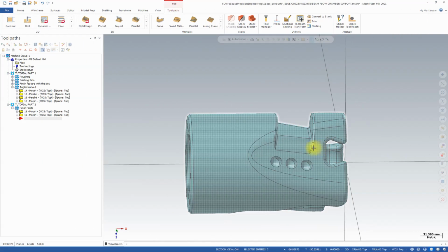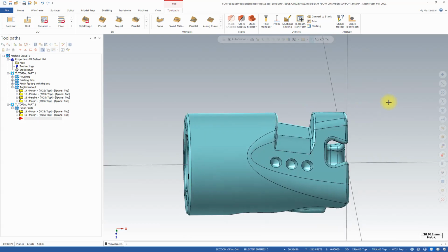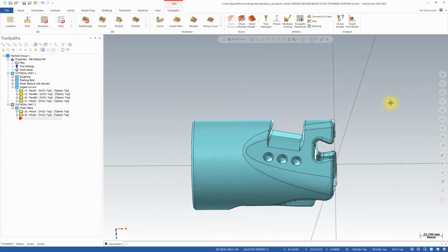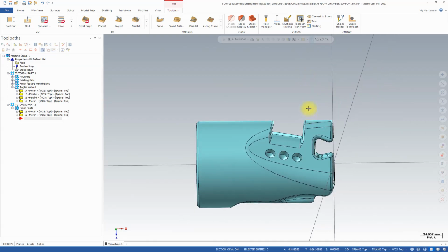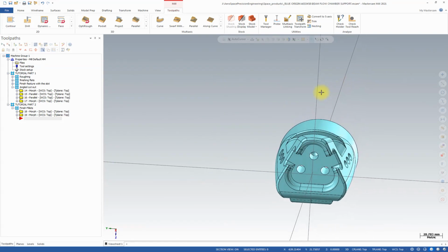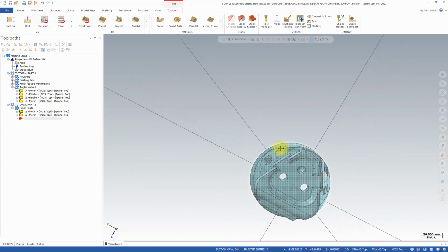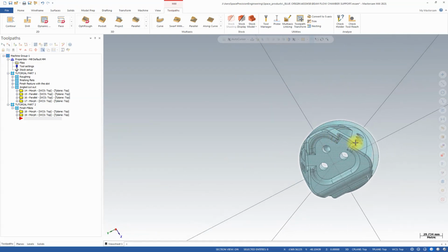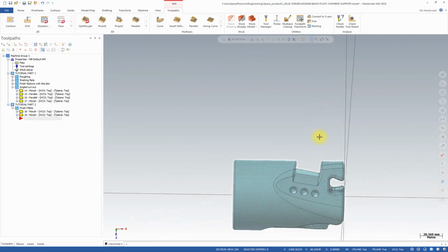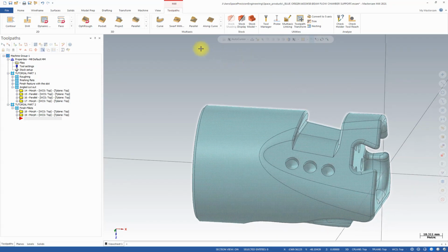Next feature we are going to cut is the top fillet here, around. And I want to use some limits because I want to keep my tool in vertical position. I don't want the tool to tilt to the front side of the part or to the back. I don't mind Integrex rotating on the Z-axis while it's cutting this area, then switch to that side. But I want tool to be kept in the vertical position. So we're going to use some limits.